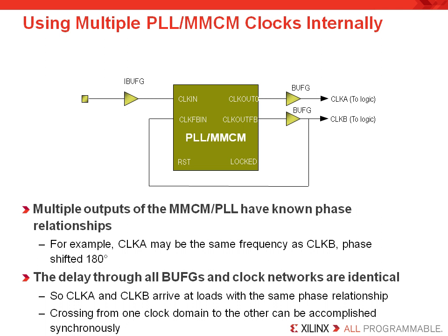Likewise, the tools will constrain the paths from clock B to clock A in this situation to 1/4 of the clock period. Now, all of this discussion is to give you some comfort that the tools are smart enough to do some timing analysis that you might otherwise have forgotten when we are sourcing clocks from a single PLL or DCM.